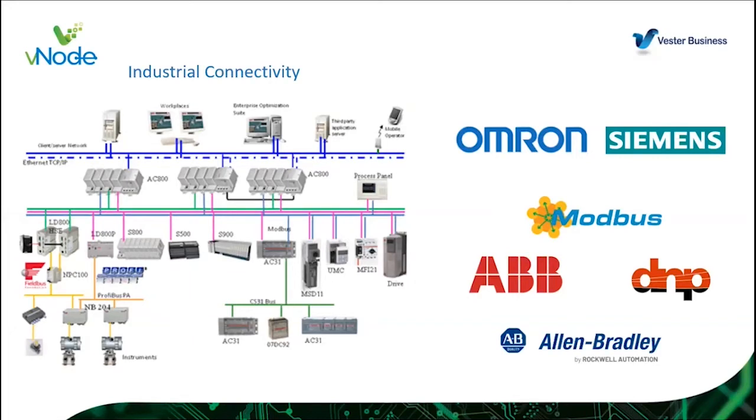And those vendors already gave those devices a way to communicate with any other applications. That is called the communication protocol, actually. So you will see that Allen Bradley uses EtherNet/IP. You see that Schneider uses Modbus TCP or RTU protocol. You see that SEL relays use their own protocol. You see that Siemens comes with its own protocol too.